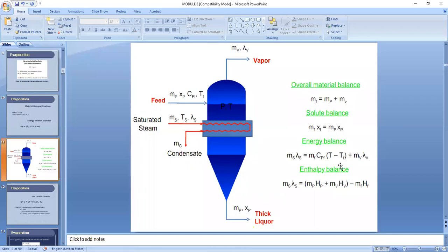Now, you may wonder, then Miss Ali, what would be the delta T, because we're specifically determining the enthalpy of the feed. What should be the delta there? So there should be what we call the reference or datum temperature. If you recall in our discussion, if we're dealing with SI units, your datum temperature is 0. When we're dealing with English units, our datum temperature is 32.